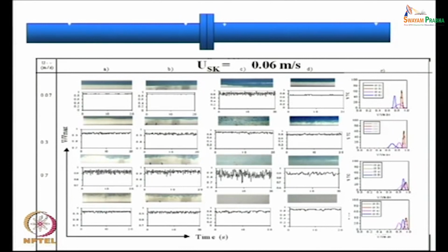So, from these cases what I want to emphasize is that we know pipe fittings affect fluid flow behavior, that you have seen in single phase flow as well, but in this particular case the influence is much more pronounced. Because why? Because whatever pipe fittings are there, they either try to homogenize the two phases, or they tend to separate the two phases.